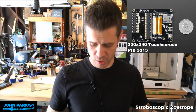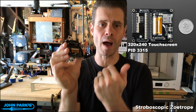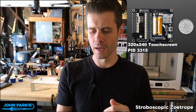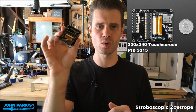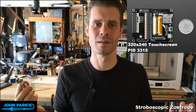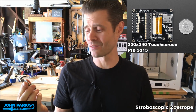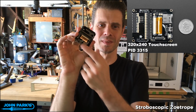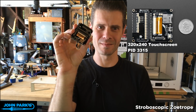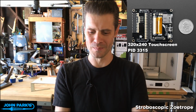And yeah, so that was the point I was trying to make: this has an on-off switch on it. That's, I believe, wired to the enable pin on the Feather. And the first time you use one of these and it's in the off position and you forget that it exists, you think something has gone horribly wrong with your code. Well, not you, but me. This happened to me. I thought something had gone horribly wrong. I couldn't figure out why nothing was powering on until 20 minutes later I realized, oh yeah, there's a little on-off switch on here that enables the whole Feather.